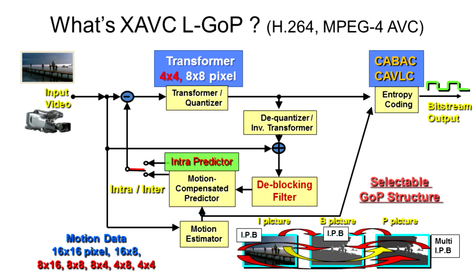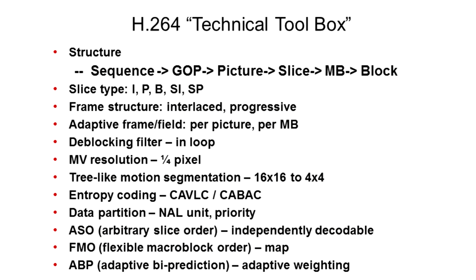This is a very complex algorithm based on the same structure of compression that we had in MPEG, but now with much more sophisticated compression tools. This is called an interframe or hybrid DCT architecture, where we have embedded multiple frames of reference that will be used to predict incoming blocks of pixels. And in each one of these areas, the algorithm had enormous technical tricks in order to improve the picture quality. Natively, this is an interframe or long group of picture algorithm.